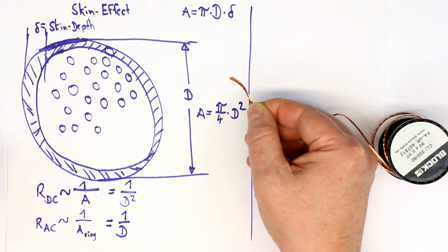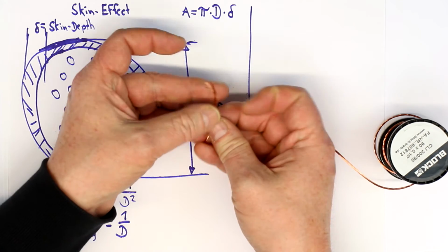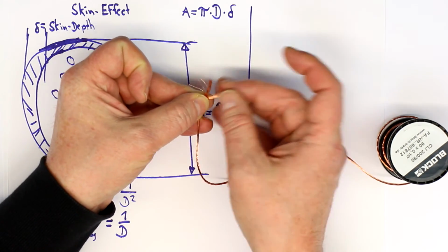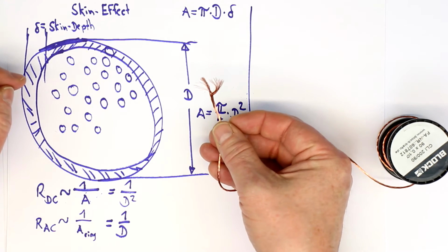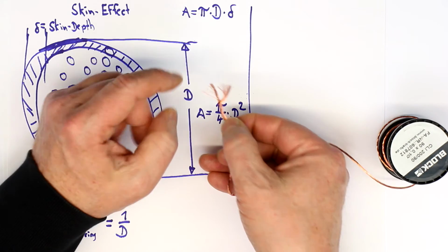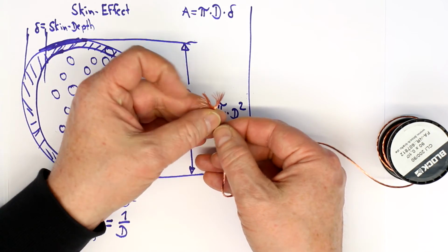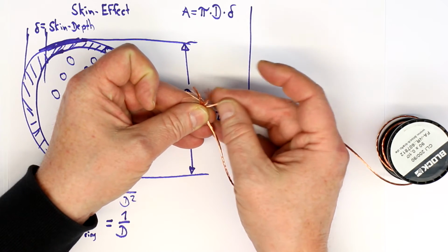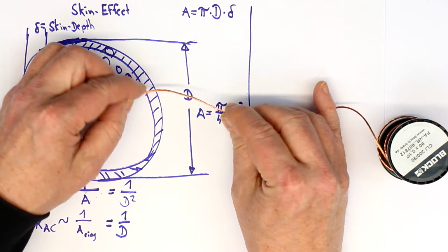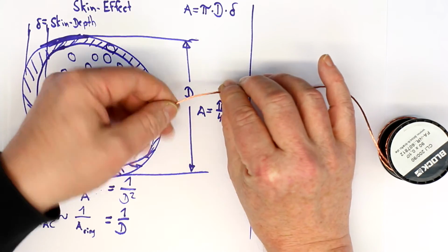So here's an example. Probably you won't be able to see it very well. It looks at first as if these are uninsulated bare copper wires, but it's not. If we would measure them with an ohmmeter, we would see that they are all isolated against each other, and perhaps you can see they are also twisted against each other.